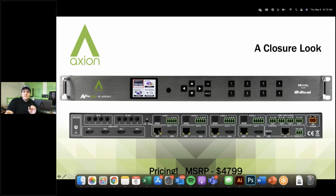So the same exact signal is coming out of this HDBaseT port that is coming out of this HDMI port. The reason that we have this is we use this as a loop out. Sometimes it may go into an audio system. Maybe you hide your AVR in the rack as well for a nice luxurious speaker system. Then you could take your HDBaseT directly to your TV, but you could keep your AVR right in your rack system and just loop right out, extracting the audio, using only the audio out of this one.